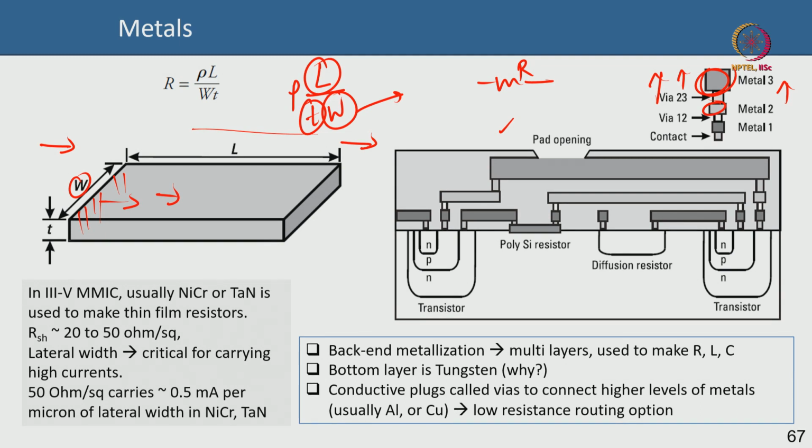So if you want to implement a resistor in a CMOS process, you can either use polysilicon as a resistor, or you can use a diffused layer as a resistor. Both of them are not very good, because they tend to depend on temperature. With higher temperature, as you heat up with carrying higher current, your mobility will degrade in the diffusion resistance, and so it has a great temperature sensitivity. A polysilicon resistor is not as good a resistor as a metal, of course, so a metal is always better.